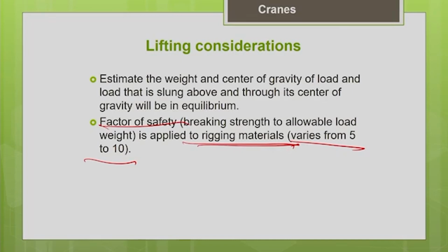So, estimate the weight of the load and the center of gravity of the load, and a load that is slung above and through its center of gravity will be in equilibrium. That you should always keep in mind. Rig it at its center of gravity.